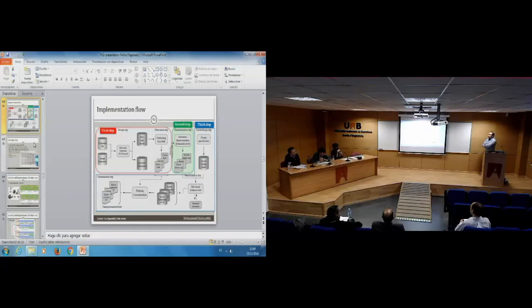I think the fact that we can use low resolution digital printing like inkjet, which is the most common and available one, and cheaper comparing to the other fabrication technologies, the fact that we can use that for uncommitted array of high performance transistors using this drop configurable structure just by leaving one drop and having a circuit built at home, not returned to the manufacturer, but at home, would be the main impact of the thesis, which is one of the advantages of IGA, bringing more functionality capabilities to the IGA.